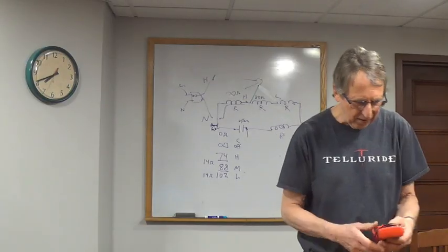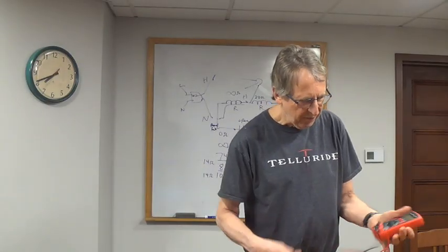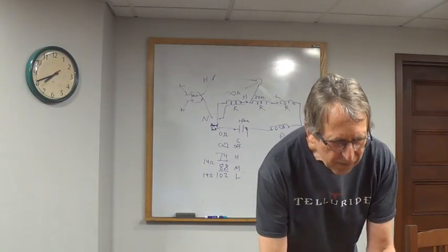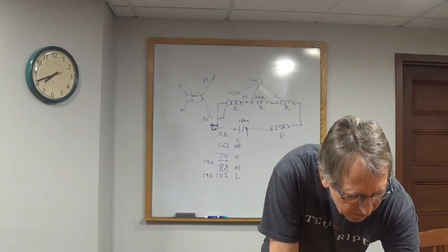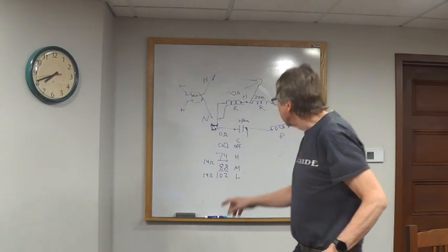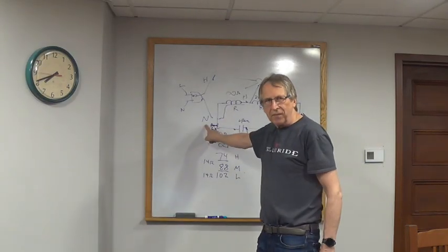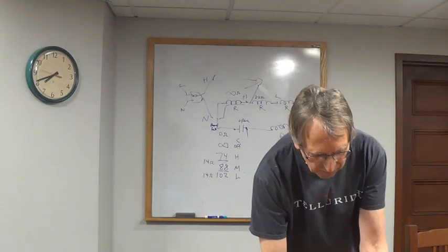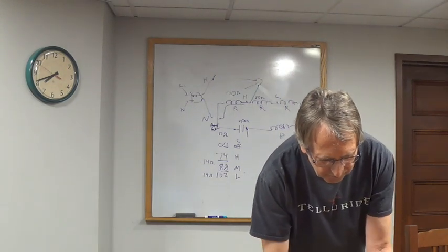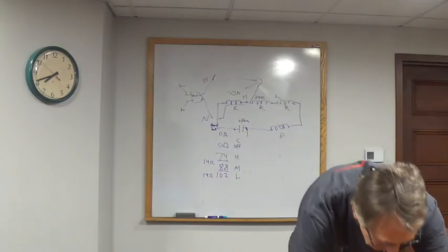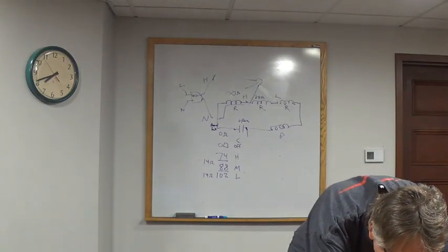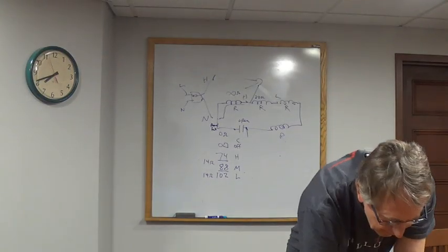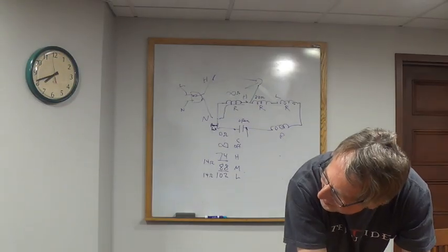So you guys may find it hard to believe, but this is how you do it. We're going to figure out which of these wires that goes to the capacitor goes directly to neutral. And the way we're going to do this is with these needle probes. I just bought them.